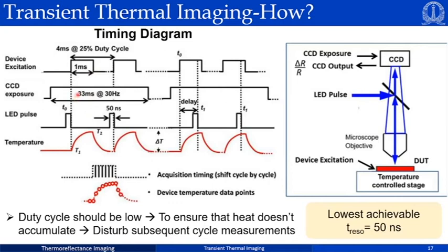Okay, so what is my goal? My goal is to apply electrical pulses to the device. And what am I expecting? I'm expecting that in response to these electrical pulses, the device current will rise, and it may or may not achieve a steady state, and then once the pulses are off, the device current will go back. In response to the device current and electric field, the device temperature will follow a curve of this sort. The temperature will rise from the ambient room temperature to a higher value as the pulse is applied, and as the pulse is removed, the temperature would then try to go back to its original value.